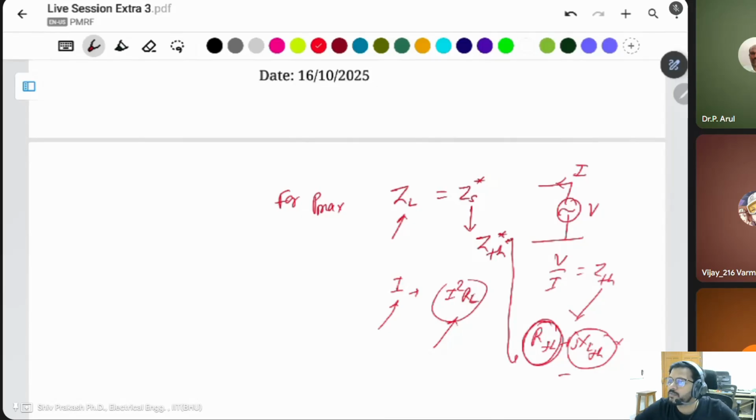Question number 7, sir. Question number 8, both are the same, I think. And question number 9: the magnitude and phase plot of the voltage across the inductor in the circuit. This is done by using Laplace. Sir, this waveform is related to the Bode plot. Yes, if you take the Laplace of the circuit and find the output voltage divided by the input voltage, then you get the transfer function. From that transfer function you can find the Bode plot.